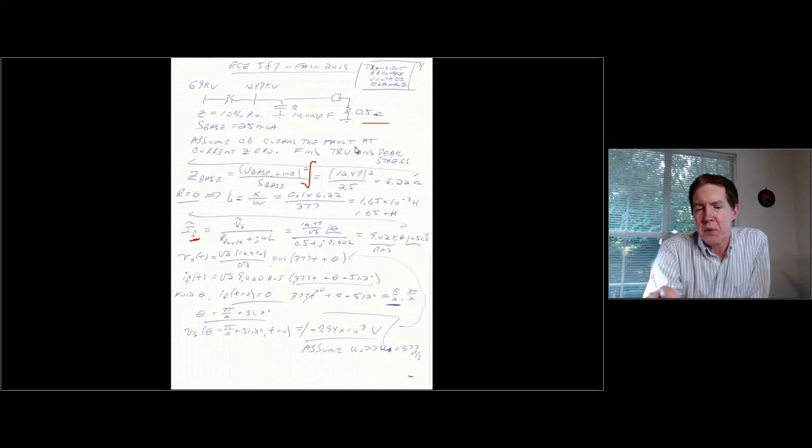I'm assuming that we're in steady state when the breaker is clearing the fault. And this is just going to be a simple RL circuit, but in this case, the resistance is going to be the resistance of the fault, that 0.5 ohms. So if I substitute in the line to neutral value for the source voltage, note this time I'm adding a point on wave value for theta.